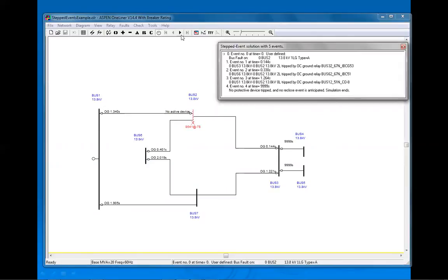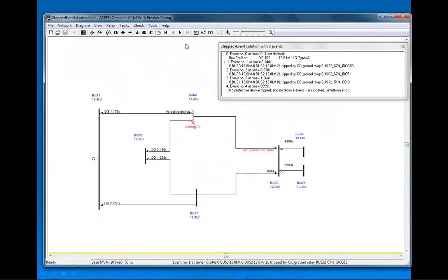First, if I play the first step, you will see that a breaker here opens, the fault is still there. Then in the next step, the second breaker opens, that prevents the current going this way, but the fault is still being fed from this end. And then lastly, only after the 3 steps, this whole thing is clear. So this is a fault clearing simulation.